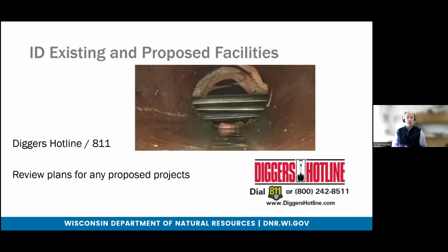Storm sewer pipes are larger in diameter, creating a much higher probability of conflict, but also they provide a direct link for the drilling fluid into local waterways if there would be a conflict or intersection with that pipe during the drilling process. A similar issue exists with sanitary sewer and water mains because of their size. And there's also a large concern, especially with water main, that potential drill mud getting into the water supply would provide a contamination of that drinking source.